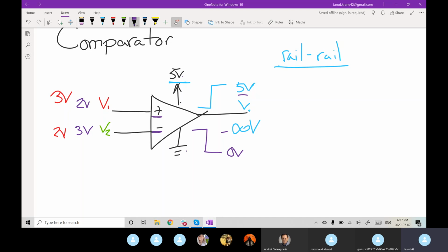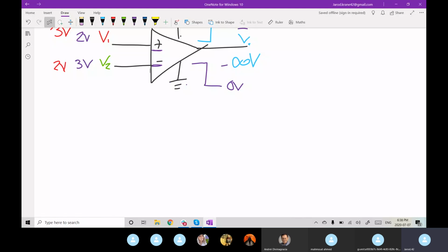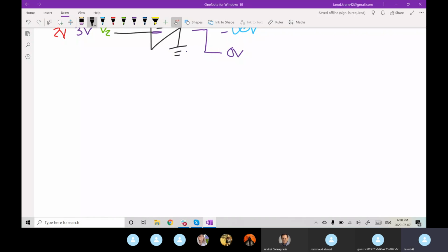Now we use this in a couple places in our car, actually. Both on the BSPD and the T-cell, where we want to trigger at a certain threshold. So we want something to happen after we hit 60 volts for the T-cell.